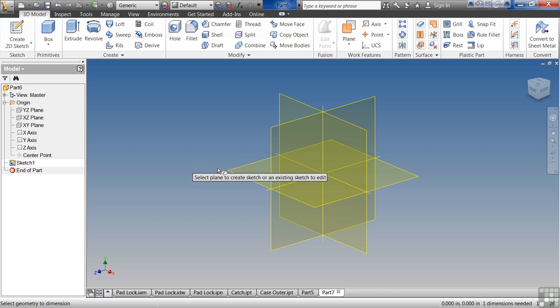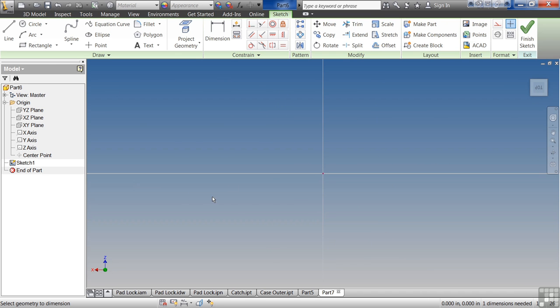Click 2D Sketch. We're going to click the Line command. As you draw, you'll notice that Inventor gives you these little glyphs. The glyphs are these little markers that tell you what it's doing. If you're familiar with AutoCAD, it's very similar to the O-snaps.